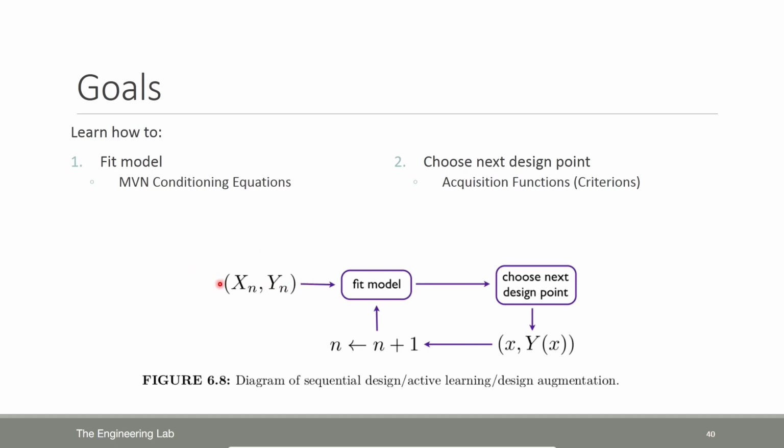Step 1, you generate the training data. You run Nastran at different configurations of your FE model. You collect all the outputs. Here we'll refer to the outputs as YN. You'll then use these to construct your surrogate model using Gaussian process regression. You use these surrogate models to construct your acquisition functions. Your acquisition functions are used to pick the next candidate point. You then run Nastran. You then update your model again, and you repeat the process again and again until you're satisfied with the improvement in the design.